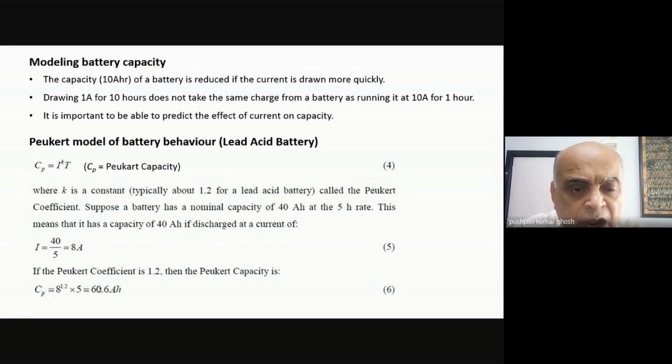So you can work out, what is your charge efficiency? It is just about 2/3, about 67%. So the total amount of charge that you put in, I didn't get all of it out.